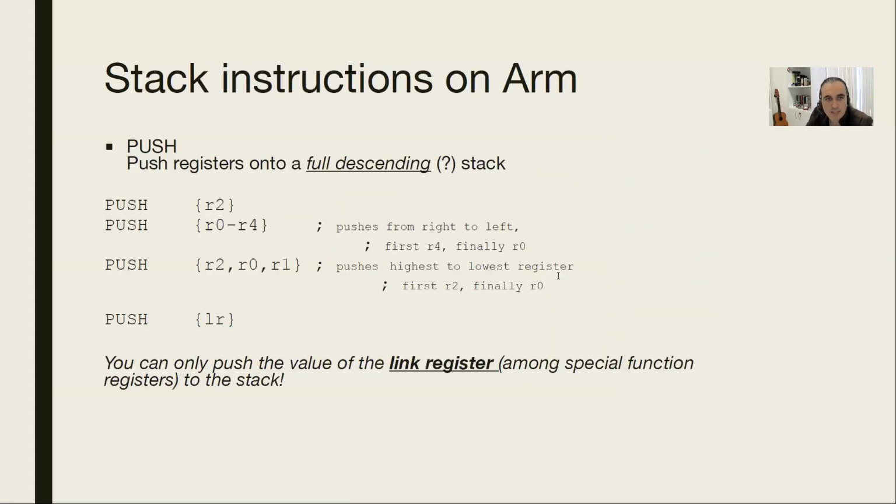Okay, so guys, what are the operations? Actually, since it's already implemented in hardware, we have instructions for it. You have an instruction just like LDR, just like STR, just like add, sub. You have assembly instructions. And to insert a variable into the stack, we have this instruction, which is push. Okay? Push means you get a register value and push it onto the stack.